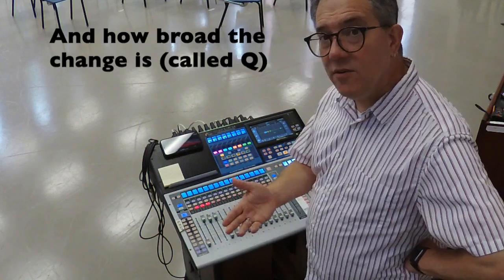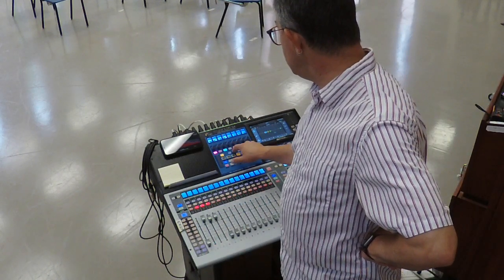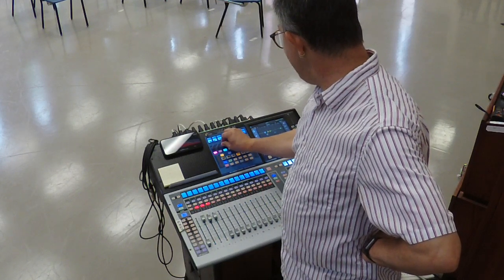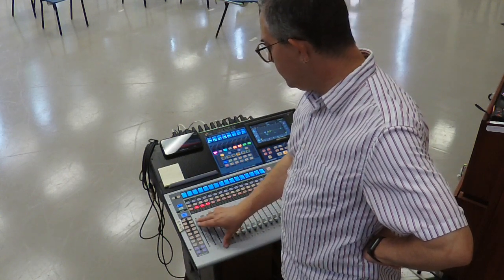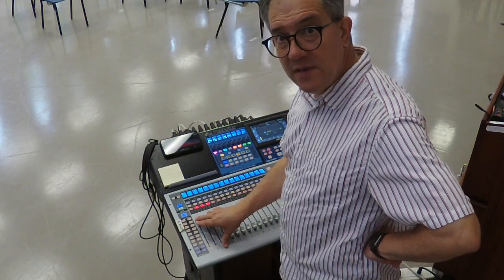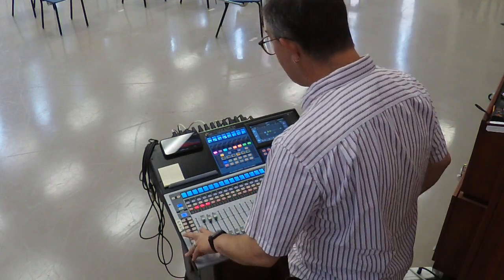So when I find that, let's get rid of that 147 hertz that tends to be ringing. I'm going to take one of my channels, and I'm going to set it to 147 hertz, and I'm going to turn it down. So now, when I start to turn this back up, you can hear that higher frequency, but that lower frequency of feedback has gone away.